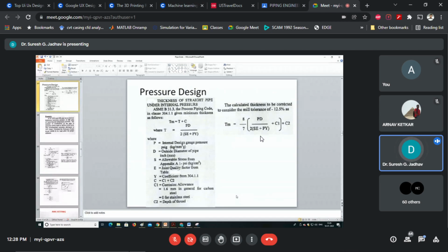This pressure should be below the maximum allowable working pressure, and based on company standards can vary from 10 to 25% above the maximum operating pressure of the system.